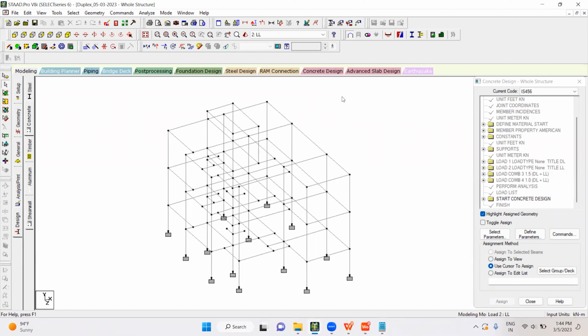So that's why the most important key suggestion is that you have to fix the standard column sizes with standard reinforcement for standard loads. Similarly, standard foundation sizes for a standard SBC like 20 tons per square meter, with standard size, standard thickness, and standard reinforcement. That you have to maintain for everything. So whenever you get the support reaction from the software, you pick the suitable foundation size. That's it. You don't need to do the design every time.